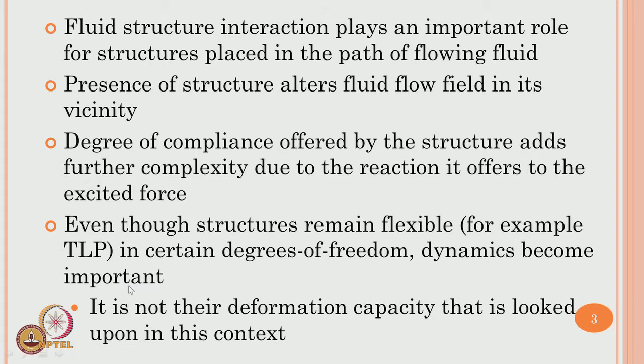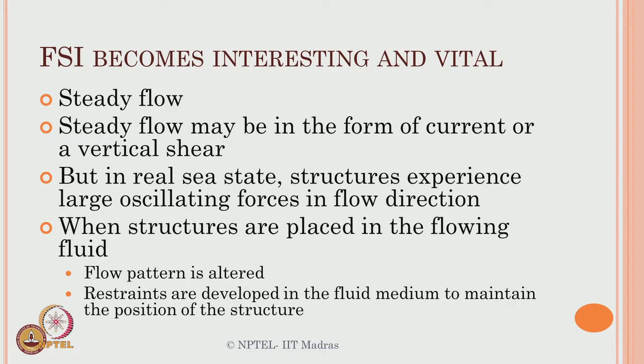Now, even though the structures remain flexible, for example, in TLP, in certain degrees of freedom, dynamics still become important, because it is not the deformation capacity that is looked upon, it is actually the vibration caused by the medium that is looked upon. Therefore, fluid structure interaction becomes interesting and vital for structures placed in the fluid medium, because it alters the steady flow. Steady flow may be in the form of current or a vertical shear, because it induces a displaced or differential pressure gradient between the upstream and downstream side, which we will see in the next slide. But in the real state, structures experience large oscillating forces in the flow direction.